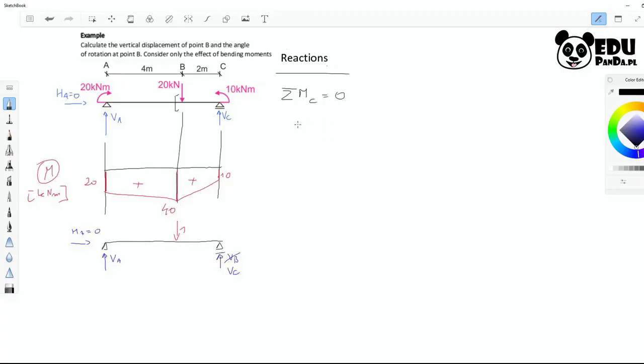What do we have here at point C? It's VA times 6 minus 1 times 2 equals 0 from this quickly. That gives VA equals 1/3. As a side note, we assume that this force is dimensionless. Therefore, VA is also dimensionless, and the moment diagrams will be almost dimensionless. There we'll have 1 or 1/3 times a meter. So this diagram will actually be in meters.